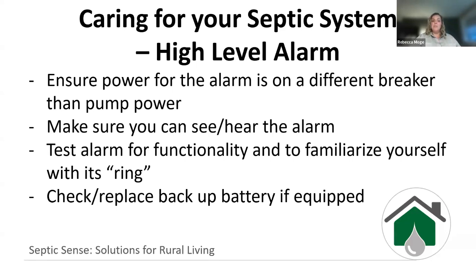Same thing as with our smoke alarms, we check them and make sure they're working. We want to check our high level alarm, make sure that it's working, that we can hear the alarm, make sure it's functioning. Because it is a very simple but effective tool to help prevent any disasters when it comes to our septic system if we're encountering problems.